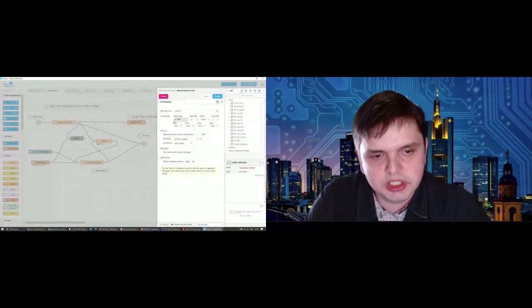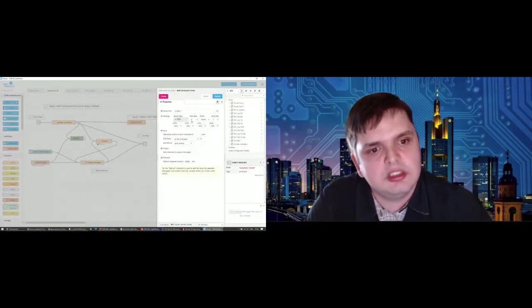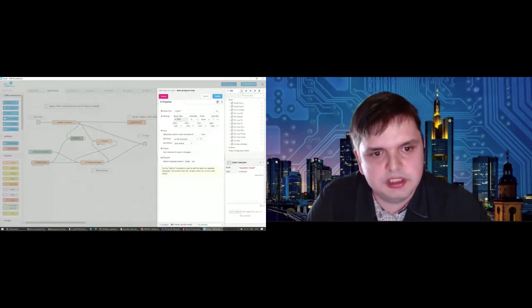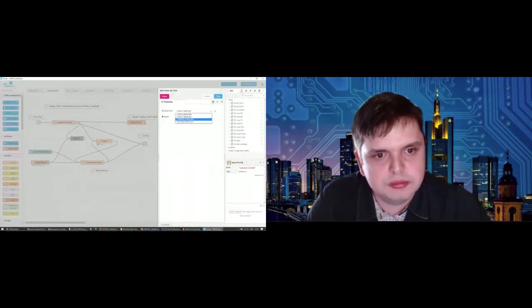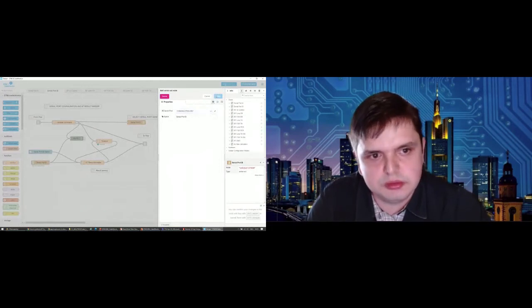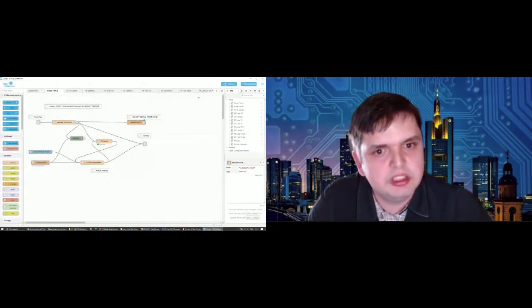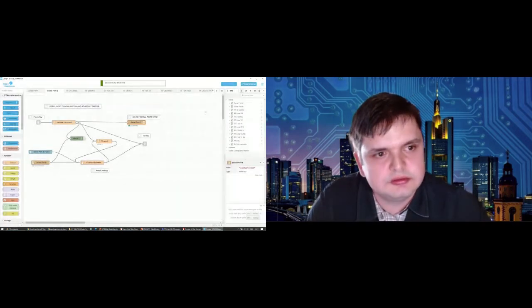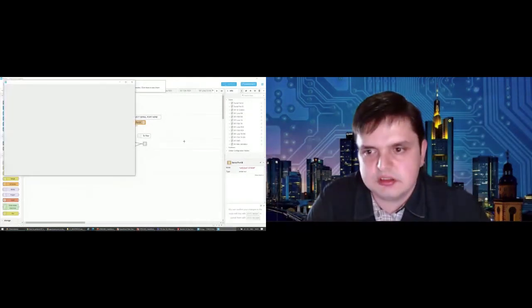So usually AT slave is on 9600, 8 data bits, no parity, etc. I will just use a dummy port right now because I don't want to block the other one, which is connected by terminal. When I have some changes, I need to hit Deploy. And then I click Dashboard to open the graphical interface.